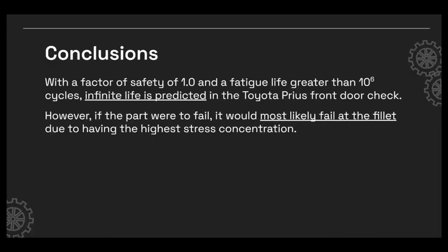In conclusion, with a factor of safety of 1.0 and a fatigue life greater than 10 to the 6 cycles, infinite life is predicted in the Toyota Prius front door check. However, if the part were to fail, it would most likely fail at the fillet due to having the highest stress concentration. Thank you for listening to our presentation.